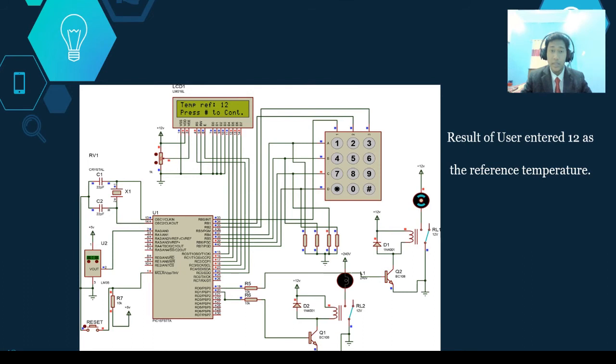The sensor itself is connected with the crystal oscillator through the OSC1 port until the RA0 port. This sensor is also connected to a push button, and the push button is connected to the microcontroller through the MCLR port. Now, after the sensor has finished measuring the current room temperature, it will send the result back to the microcontroller and then display it on the LCD.